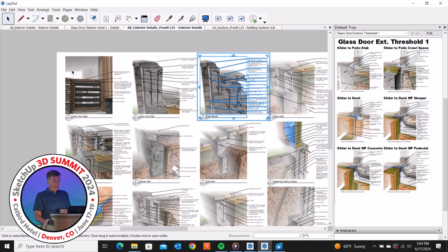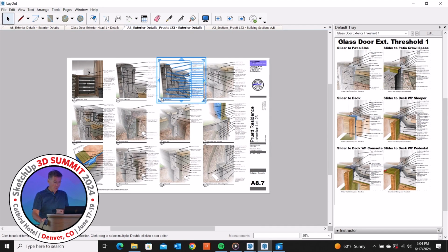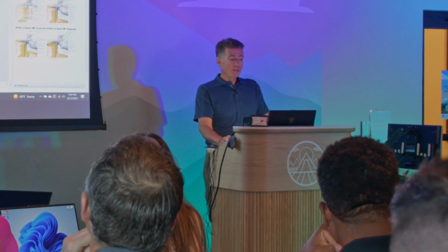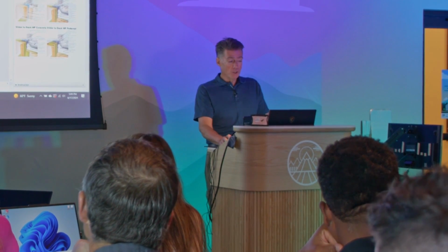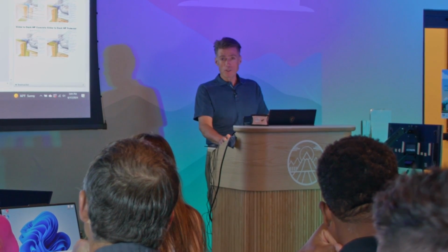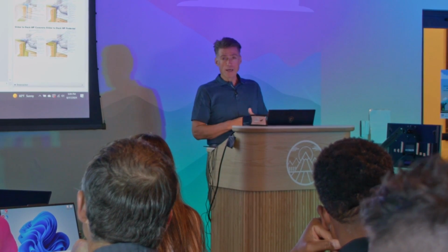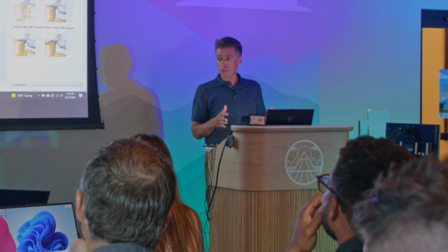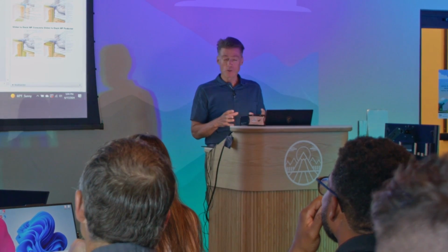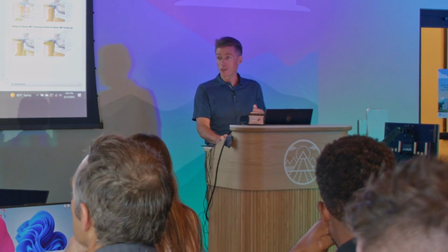And so that's the goal of this, is to give them all that little bit of detail. Did my sections open? There they did. That I don't want to necessarily show at 1/4 inch. So I keep my sections very light, and these are all referencing the SketchUp section file, which the only editing that happens in that is the placement of the section plane and the creation of the scene. I don't edit the model at all. That's only done in the main model and then referenced back into the SketchUp, or the section model.